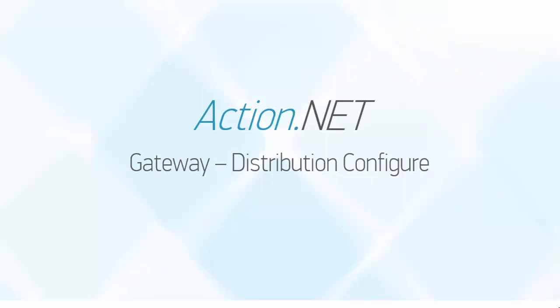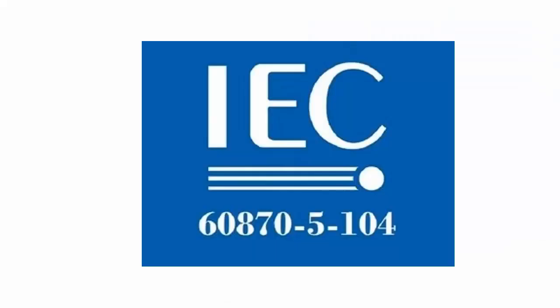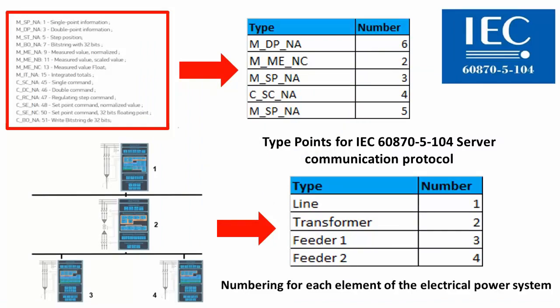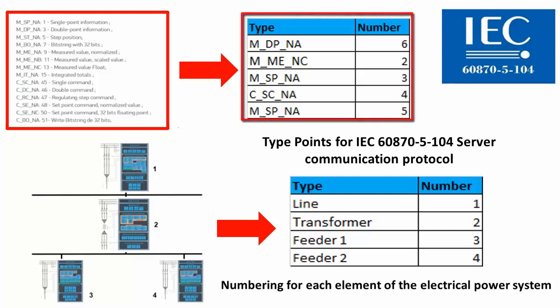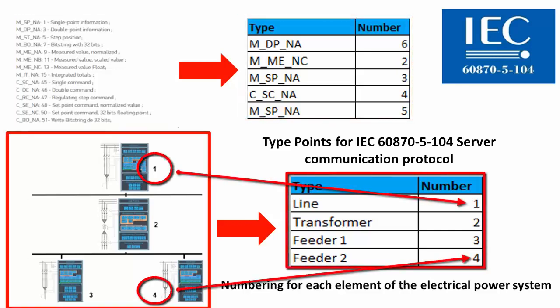Any server protocol can be used. In this example, we will use the IEC-104 protocol. The generation of the IEC-104 server point address is defined within the application. In this example, a number was considered for each ASDU used, see Table 1, and a second number for each ID associated with a bay, Table 2.